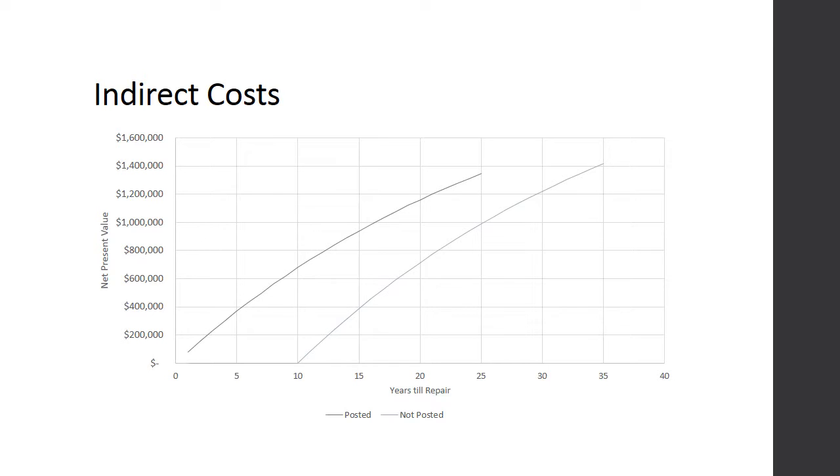The information gathered does not differentiate the types of trucks crossing bridges, so it was assumed to be a 50-50 ratio of each type. For the purposes of this assessment, the number of trucks is considered to be unchanging over time. It is clear by observing the increasing user cost over time that when coupled with the direct cost of bridge repair or reconstruction, the overall costs are minimized by keeping a bridge unposted, whether it be by repairs or reconstruction.